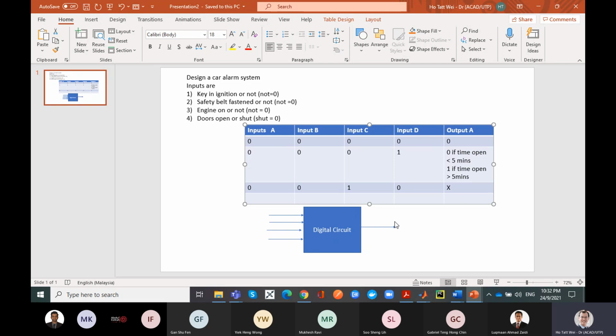Your circuit is actually going to get an output, because if you only were to consider certain parts of this circuit, those conditions which you never considered about the input will be a don't care, and then your particular implementation or the solver or the synthesis will assume some kind of output, right?